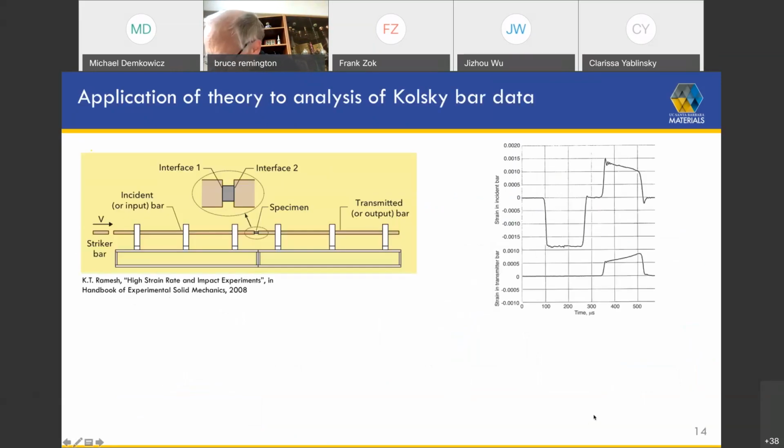All right. With that rudimentary mechanics, we can go about analyzing everything about the Kolsky bar. Okay. We have, recall, a collision between a striker bar and an incident bar. We have transmission of stresses across the boundaries with the specimen. We have transmission of, and we have a reflection there as well. We have transmission of that stress within the transmitted bar.